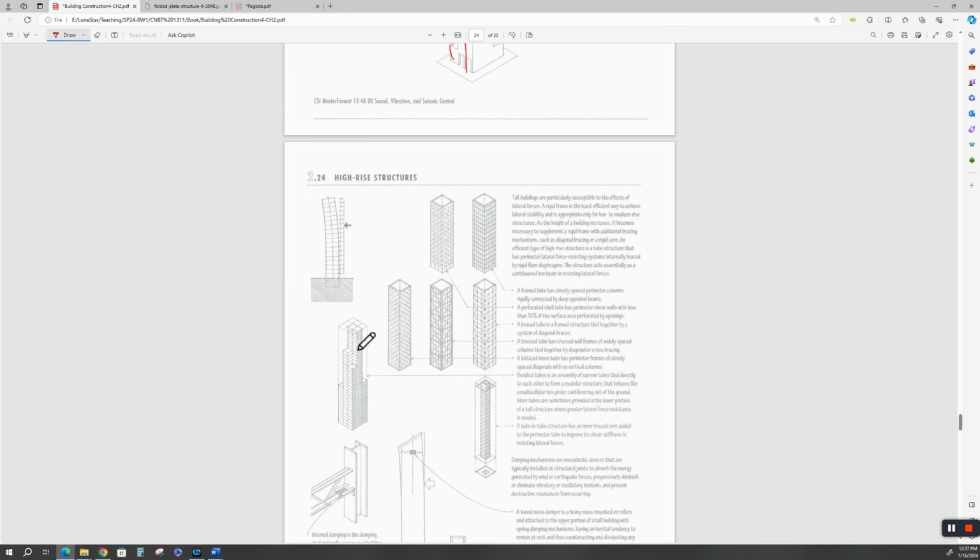The Twin Towers in New York were a bundled tube concept. I have a video of how that was built and designed. Part of it was rigid, and the rest of it was meant to flex and twist and turn because it was so bloody tall. So a traditional rigid frame is not as efficient simply because of the expense. It's appropriate only for low to medium rise, and I agree with that from my experience as an engineer.